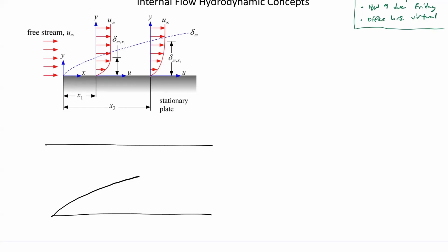So here we have our boundary layer growing, and then from the top, you're also going to have a boundary layer growing, and eventually they're going to intersect. And at that point, the flow characteristics change a little bit. The boundary layers can't continue to grow. They are constrained in that way, and so we have to come up with different relationships that specifically deal with this region. So for vocabulary, we're going to talk about over here, this is the